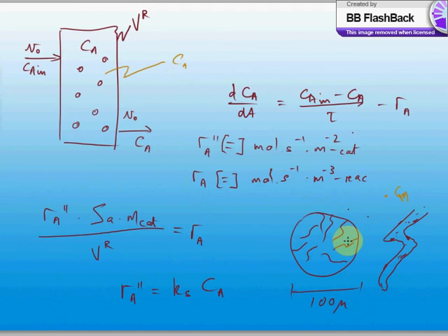And there are two layers of mass transfer resistance that the particle might offer. So first of all, we might have difficulty in diffusing to reach the surface of the particle in the first place. So our external mass transfer might play a role. And then once we start diffusing into the particle, right into the pores here, there might be some additional mass transfer resistance.